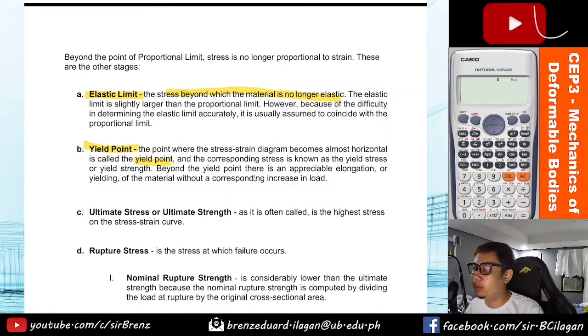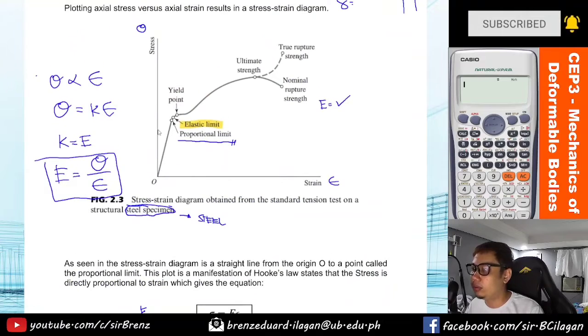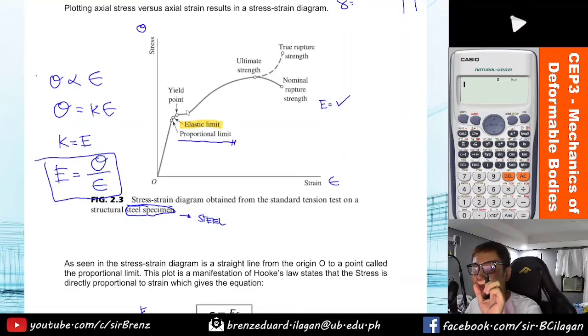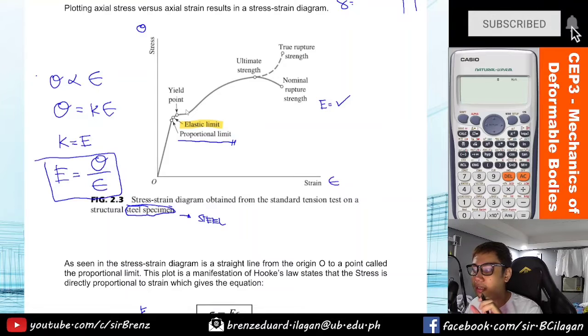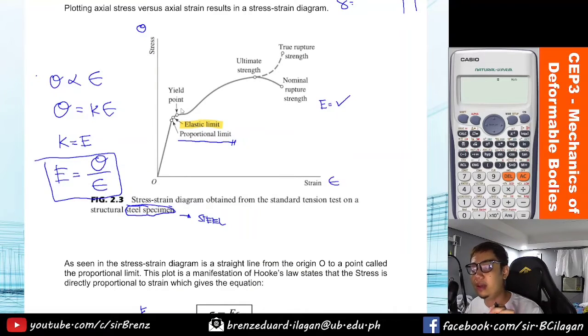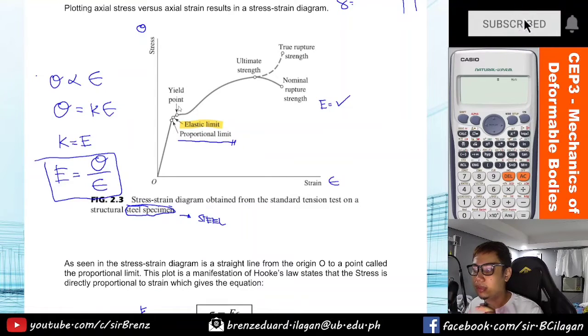So, beyond the yield point, there is an appreciable elongation or yielding of the material without a corresponding increase in load. So, without increasing the load, naging almost horizontal na siya. Meaning, even maliit na force na lang yung i-applied mo, ma-observe mo dyan na there's a deformation, a big increase in strain considering na maliit na force lang yung ina-applied mo, or a small increase in force which results in a big or higher value of deformation or strain. Okay, so kaya naging almost horizontal siya.